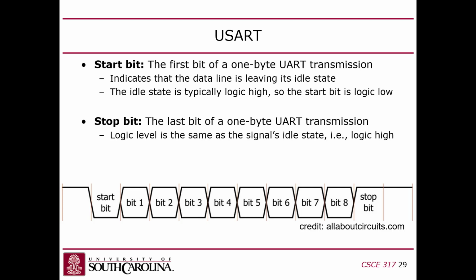And then from there, you send each of the bits over from right to left. Generally, the stop bit is a 1-bit time where you return the bus back up to high state. Now you can also optionally have a parity bit that's used for error detection. If you have the bus configured with parity, the parity bit would come after the most significant data bit, but before the stop bit. And the parity indicates whether there was an odd or an even number of ones.